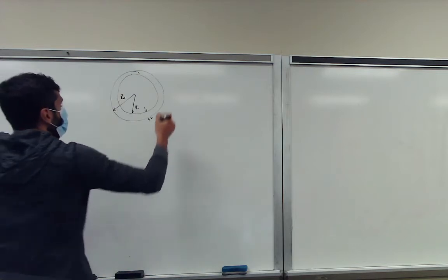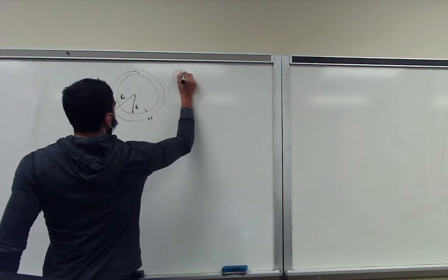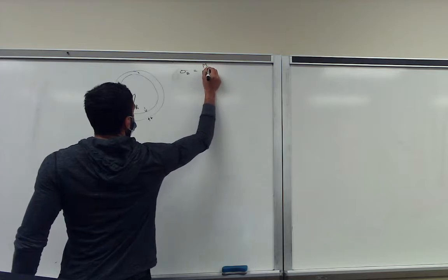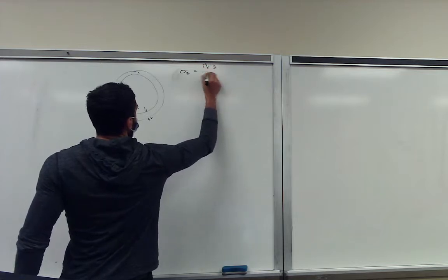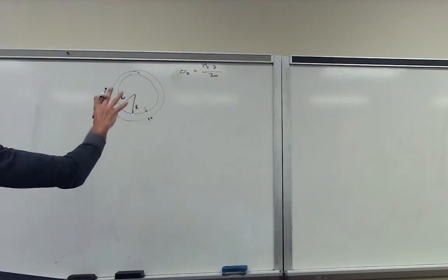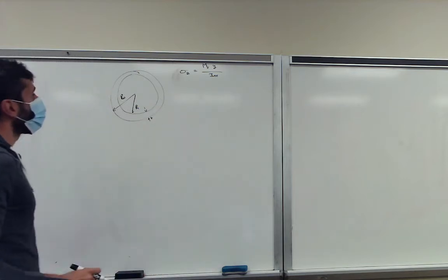So from moment of inertia, we know that, first of all, the stresses, if it's pure bending, is Mx multiplied by y over Ixx. So moment and the y location, those are basic standards, so we need to determine the moment of inertia.